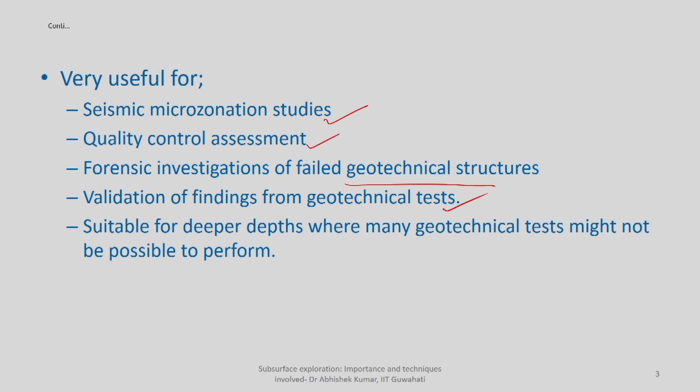Then it is suitable for deeper depths, where many geotechnical tests might not be possible to perform. As we know, SPT, CPT, and dilatometer tests each have some limitation in terms of the depth of exploration. So if your depth of influence is more than that particular depth of exploration, there must be some other ways with which you will be able to determine what kind of subsoil properties are there, what the physical properties of the medium are, and what the soil types are. So in those cases also, particularly for deeper depths, geophysical investigations are very important.